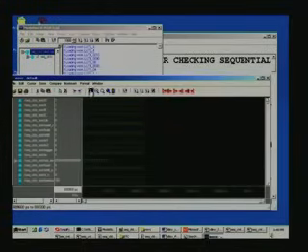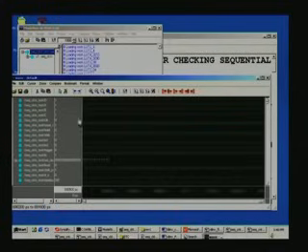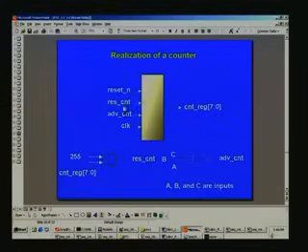So, this is the waveform that we have, and in order to analyze, we will take just one example, and in a similar fashion you can analyze other functionalities. You remember, this is a sequential circuit. We had, let us say, a counter, just a simple counter, which advances right from 0 through 255 and revolves around that, and it can be reset for certain conditions when counter is equal to 255, and can be advanced if ABC are each 1. So that's a simple counter.